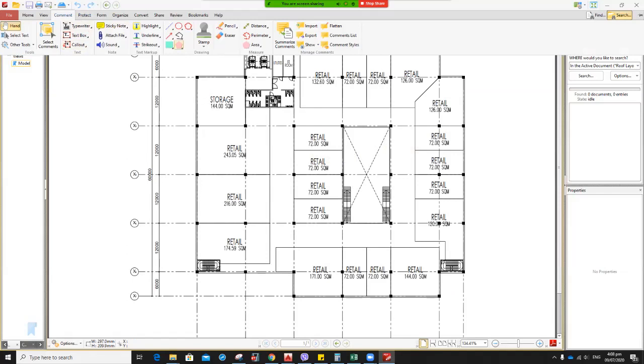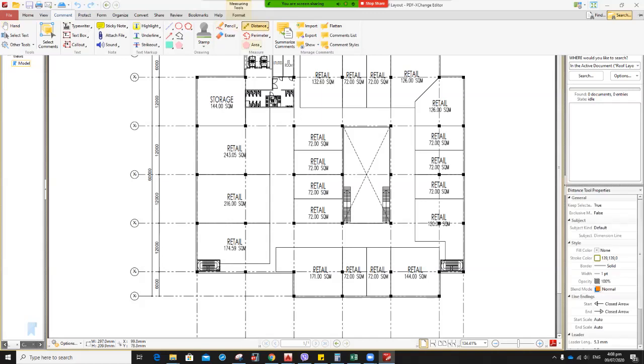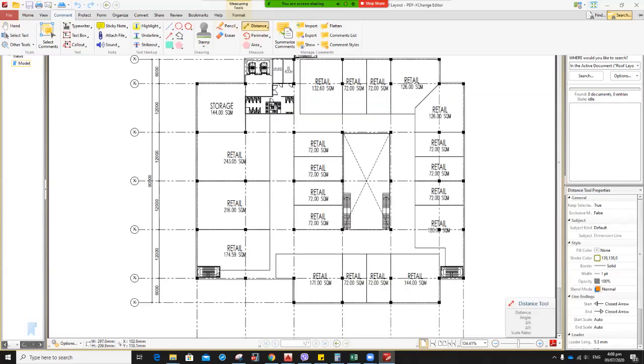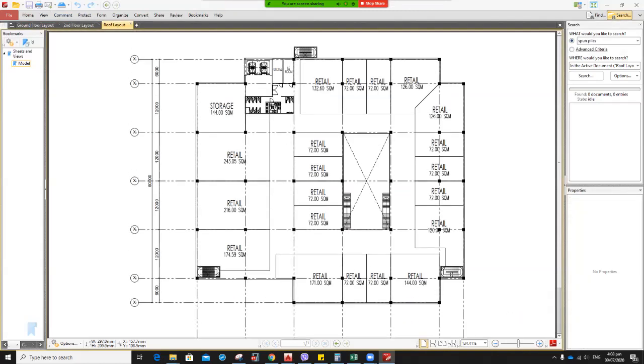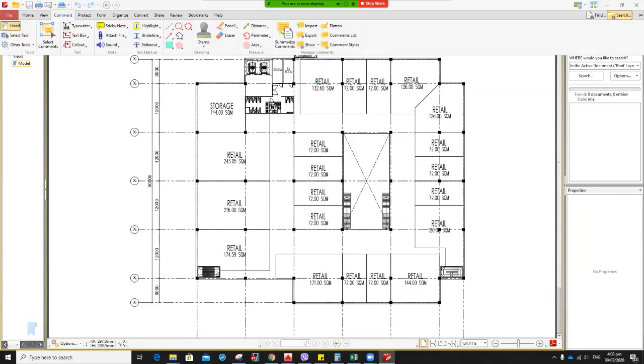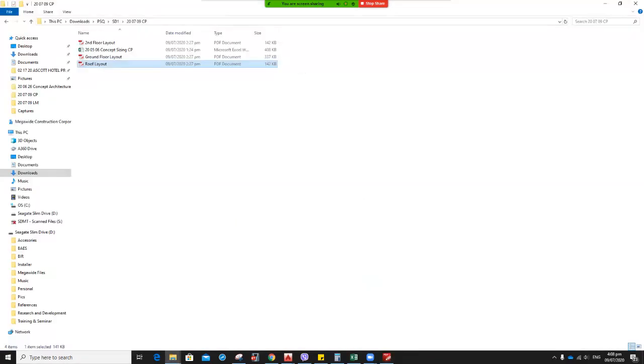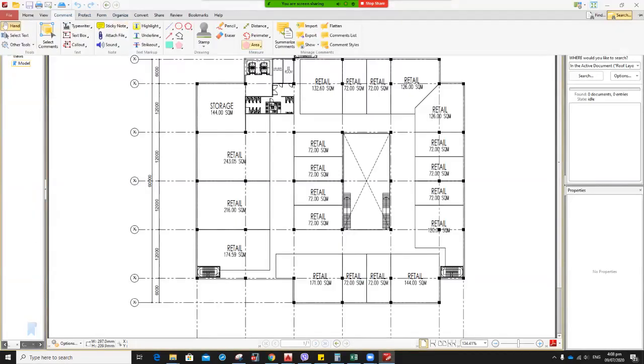So for the framing system, the best is to start it from top, because the topmost will be supported by the ground floor. So when you're doing the framing, it will be best to start it on top, then verify it along the way. Okay, so let's start marking.